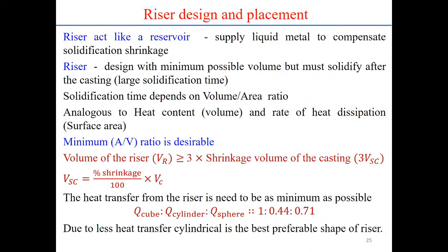Now somebody asks about the riser design and placement. Actually, the riser is very important in the casting process, and the very simple reason for using it is that it feeds the molten material. So in principle, the riser should solidify after the solidification of the cast volume.